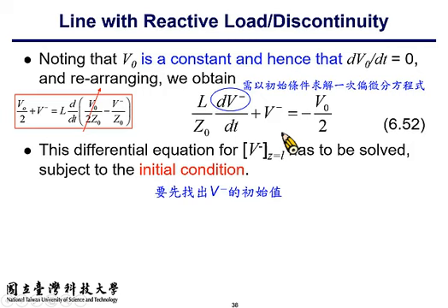And because the boundary condition is changed, to satisfy the boundary condition defined by the inductor, you shall have a V minus signal and I minus signal, so that the overall voltage on the inductor satisfies the boundary condition. Okay, so the unknowns are V minus, the reflected voltage, as well as I minus, the reflected current.